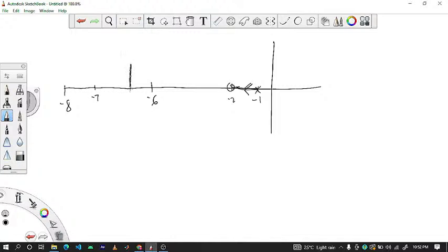One of our asymptotes is moving along the 90 degrees. The other one will move through 270 degrees. I have it like this. I got my breakaway point to be minus 6.98. You see that the root locus will emerge. It will come from the pole. So there's one pole here. There's another pole here. So it will come from here. Fine. It is moving in this direction. Get to this point. Move from here. Get to this point. Now, when it gets to this point, what happens to it? It must break away and go to the infinite zeros.